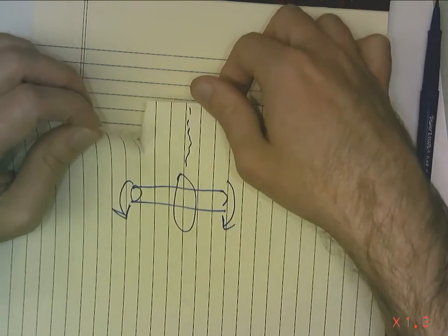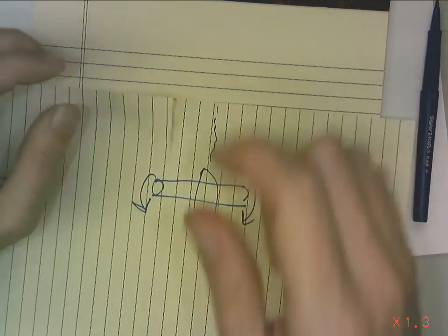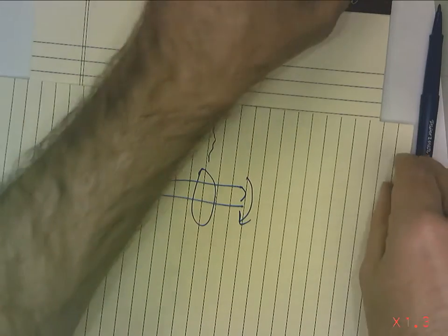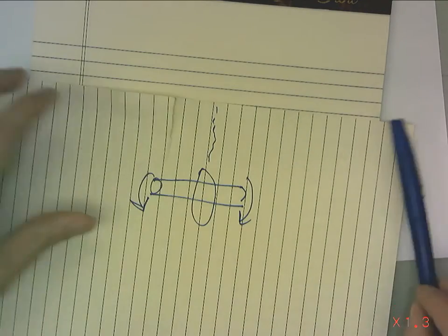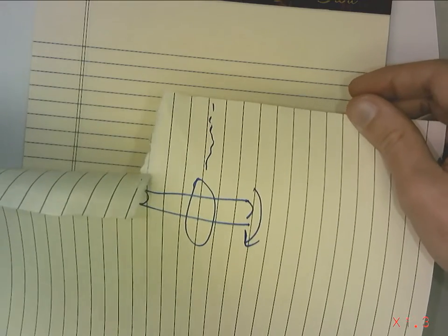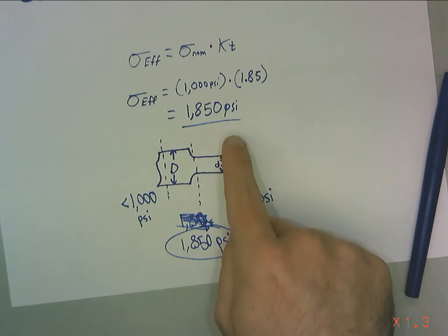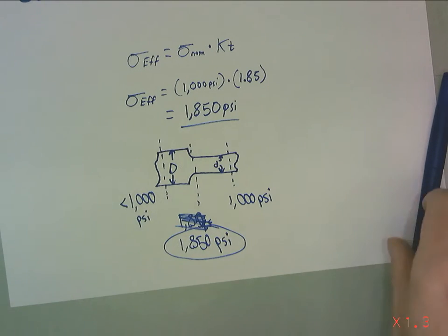But it's tearing off over here. Why? Where's the stress concentration there? And we all know the spot where it's already torn or breaking is the spot where a component is going to continue to tear or break. So we already knew what stress concentrations were. We just hadn't put any math to them yet.